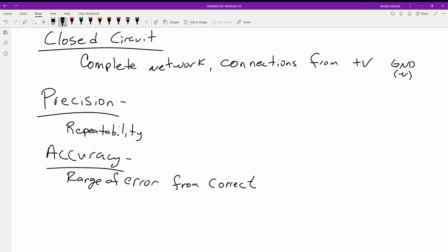So if we're using a resistor like the 1 or 2 that was in our lab, the testing wasn't very accurate, should we just use the labeled value? Yes. If you can't get a very accurate number, you can use the average of the values that you get. Once you get outside of those values, everything should lock in pretty close. A lot of times we're not going to have you do a circuit that uses a 0.67 ohm resistor. There may be stuff that you design that needs that, but if you're down that precise, you're close enough for all intents and purposes in this class.